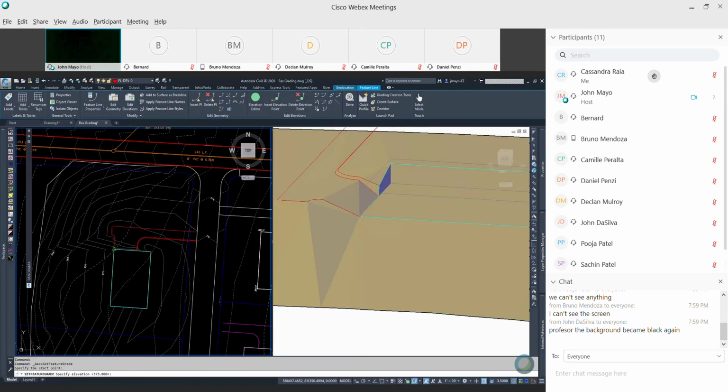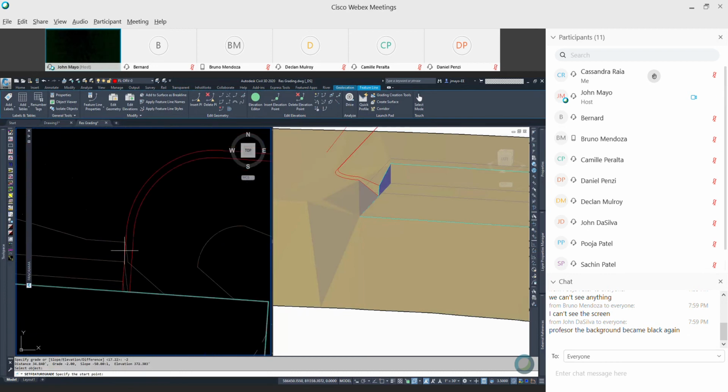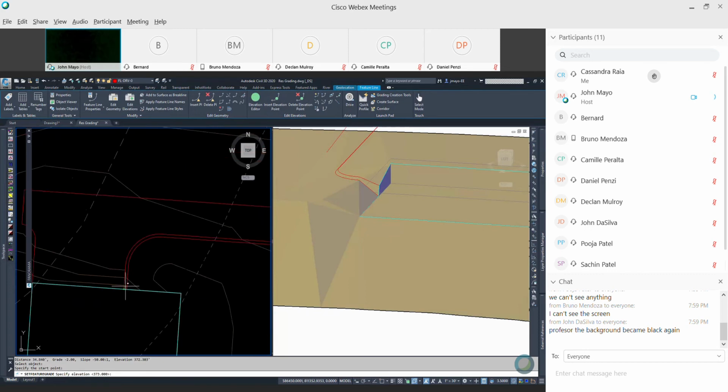And I start here, and I come down to the bottom here, and I said your maximum parking area can be 5%. And you generally want that away from the house. I'm going to start here with something a little more normal. I'm just going to go down -2%. And then I'm going to do the same thing at the other side of the driveway, but I'm only going to come to that curve, the end of the curve.